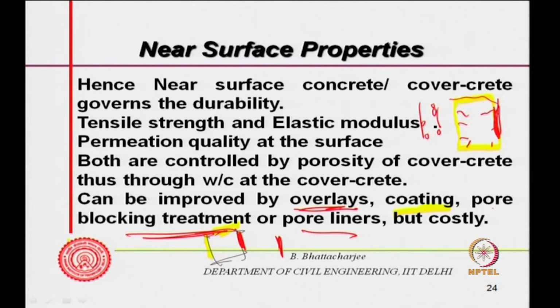So, these pore liners, pore blocking treatments are actually waterproofing treatments, and if water does not go in, then obviously durability will be enhanced. So, cover concrete can be improved in this way. At the moment, of course, we talk in terms of water cement ratio and cement control, but some of them could be costly.